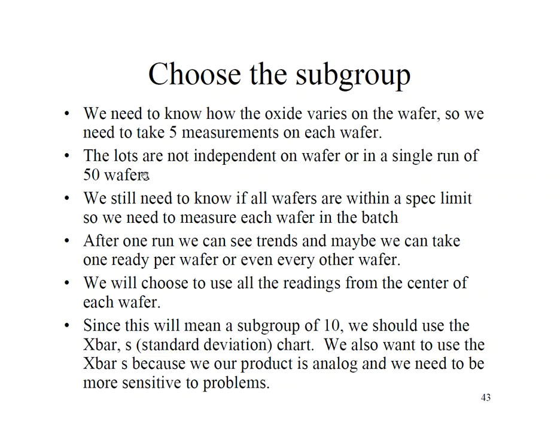So I might have 50 wafers going in the furnace at the same time, but the variance across a boat isn't necessarily random. So you might take the average of all the wafers on a run, and that becomes 1 point. So if you have 10 wafers, 5 points, 50 points, the average of that and the range of that becomes 1 point on your data, on your control chart.